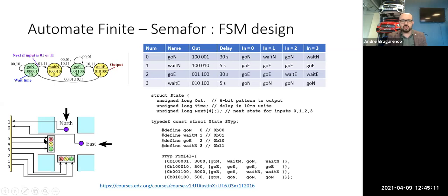And we have 2 traffic lights with 3 LEDs each, connected like this. The least significant bit, LSB, is connected to the green, after that yellow, then red for the north direction, and green, yellow, red for the east direction, where the most significant bit, the 5th, is related to the red of the east direction. So we'll have something like this.